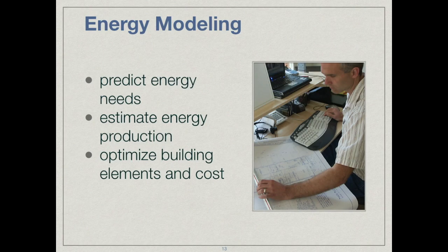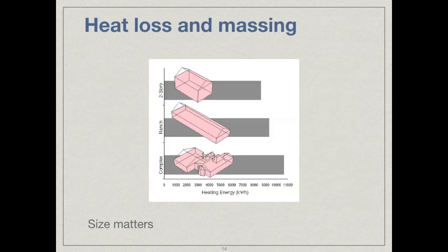Do I need to go to a triple pane window, or can I use a really good double pane window? So the energy modeling step is super important when you start the process, and is a way to not only optimize the techniques and the materials in the building, but also the cost in the building.